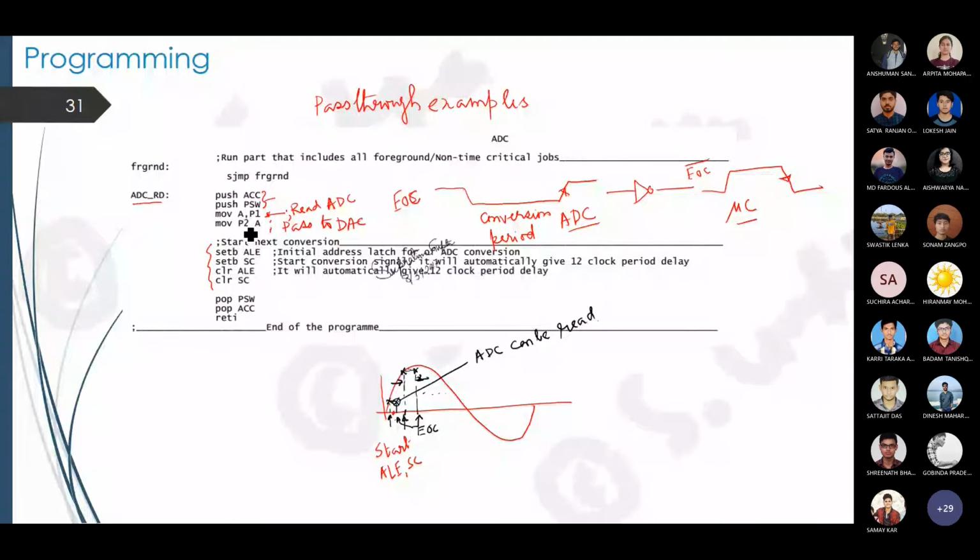You see, this P1 is read, then you have transmitted, and the DAC is complete hardware. It will work immediately, in a very short span of time. And then you are again starting that. Then again this will take, say, 100 milliseconds or so. Before 100 milliseconds, you already get this DAC output, because this is not a software one. So the delay is very small.